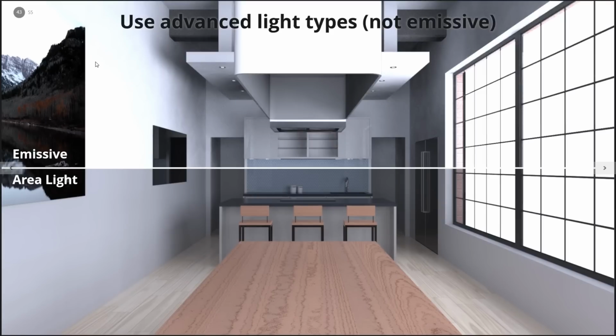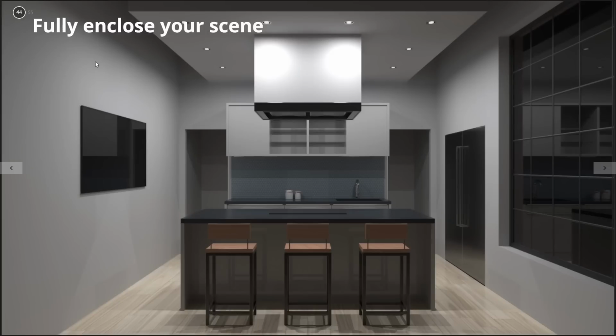And here is side by side. It's actually up and down, but here's a comparison of rendering a scene just using the emissive material and just using the area light. So only physical lights, no environment, nothing like that. The top half is emissive, and you can see how splotchy it is. Everything in the scene otherwise was the same: material, samples, render settings, but one is working with the emissive. Up top, it's splotchy and bright and kind of funky. On the bottom, that's our area light. So kind of a comparable amount of light put out for each, but the area light is going to give us much, much more consistent, realistic lighting. So yeah, that's one thing. Don't use emissive, use the advanced light types.